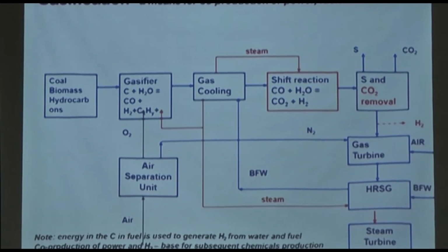But for gasification, you need to supply substoichiometric air. If you are running the gasifier at higher pressure, then you need to supply pressurized oxygen. That can come from the air separation plant, and this is a very energy intensive operation.